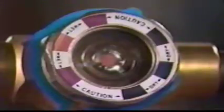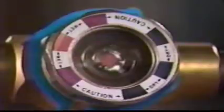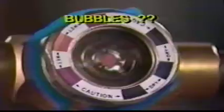It is the liquid line moisture indicator that will tell the technician if moisture level in the system is too high. The indicator has a moisture-sensitive element that changes color as moisture content in the system changes. A color scale on the indicator gives the technician an accurate reading of the moisture level in the system. For convenience, a specially engineered chemical element works with all the common refrigerants. The fused viewing glass permits easy inspection of the system refrigerant so that bubbles or flash gas are easily seen.